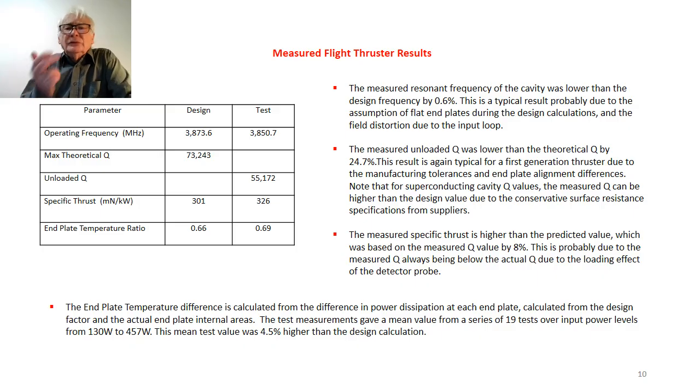But also, quite interestingly, when we did some very careful internal plots of the fields within the cavity, we found that there was a small amount of field distortion around the input loop. And this also contributes to the difference between the test frequency and the design frequency. And we have noticed that this is consistent with a pretty consistent error rate across a number of cavity designs.